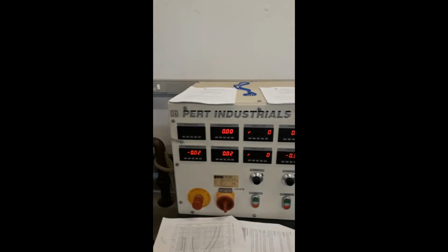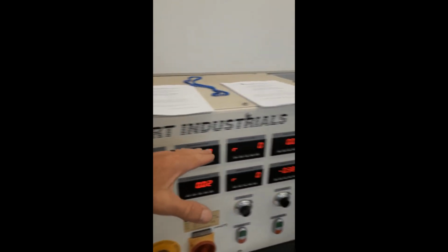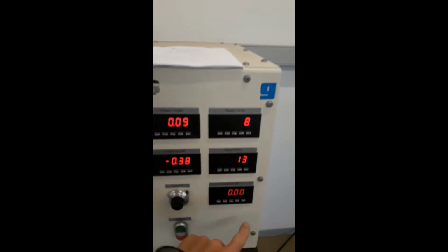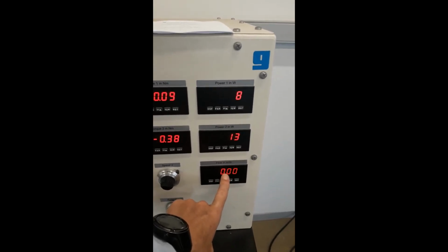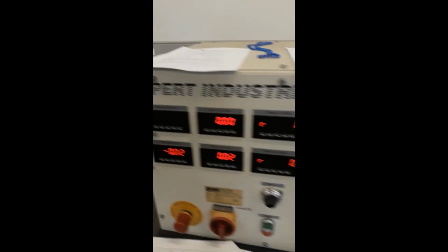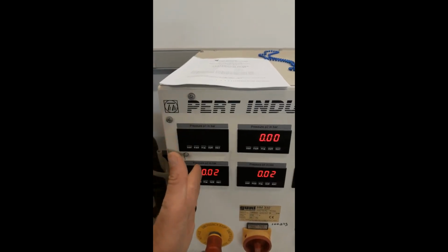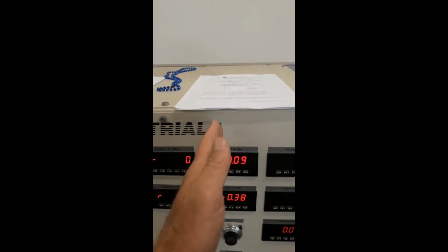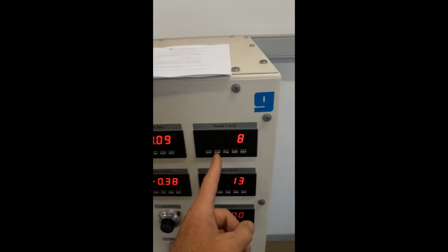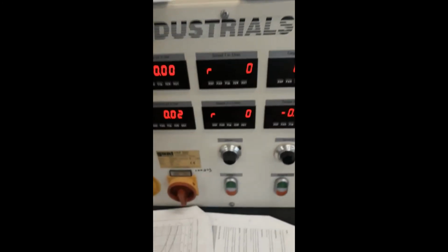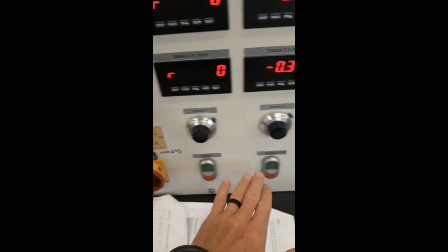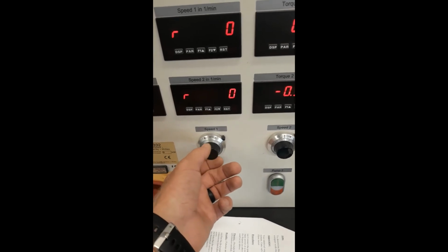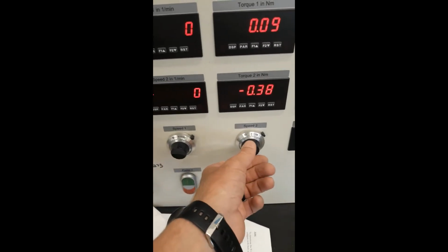Then the control panel. The top numbers is for pump number 1, and the bottom numbers is for pump number 2, and this one sitting here by its own is the flow meter, because we only have one. Then this is the inlet pressure, that's the outlet pressure, that's the pump speed, this is the torque, and this one is the electrical power in. Also we'll have here the on-off buttons for pump number 1 and pump number 2, and this is a variable speed drive, so we can adjust the pump speed for both pumps.